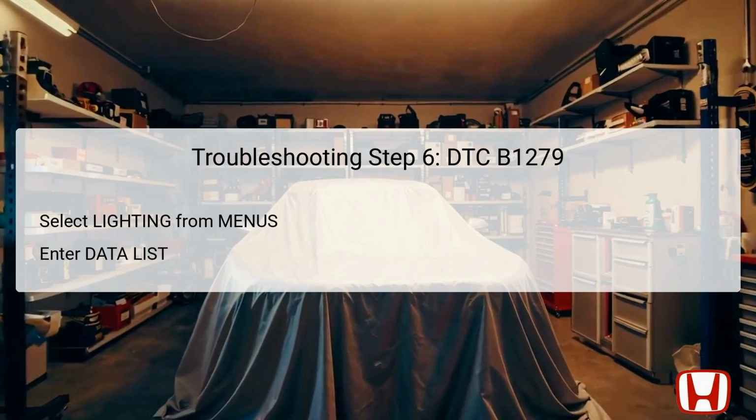In this step, navigate to the Body Electrical System Select menu and select Lighting to enter the data list. This process allows you to access crucial diagnostic data pertinent to the dimmer switch and combination light switch. The data list will provide values that reflect the status of the switches, confirming whether they are functioning correctly in real time. Accurate readings from the data list can illuminate potential faults not apparent through previous visual inspections.